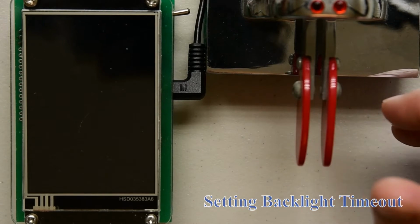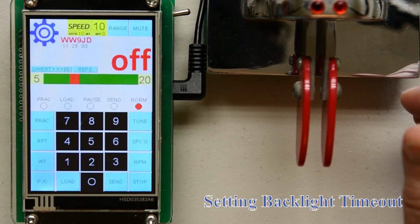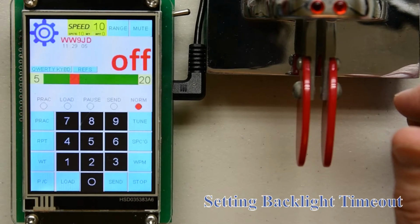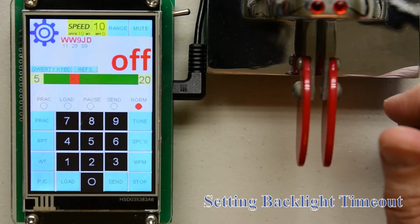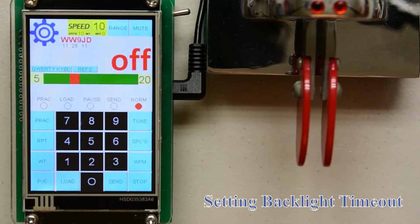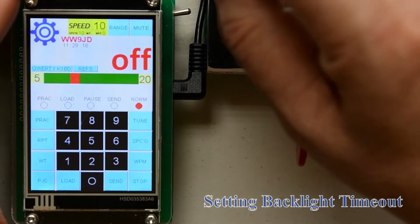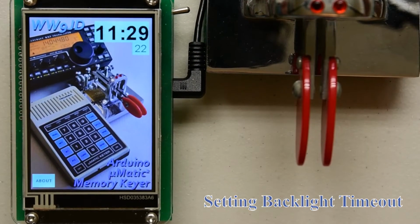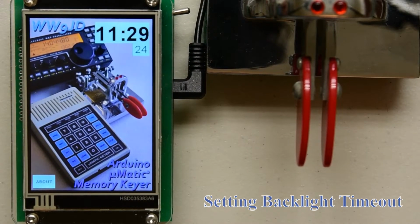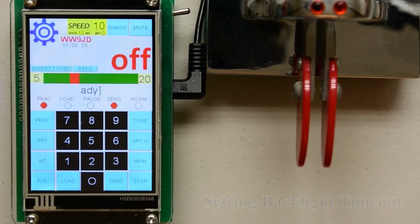To turn the display back on, tap someplace on the screen. That brings the display back up. It will cycle off after another 30 seconds without any taps on the screen. To stop it from cycling off every 30 seconds, you'll have to turn off the keyer and then turn it back on. The sleep setting cannot be saved from power off to power on.